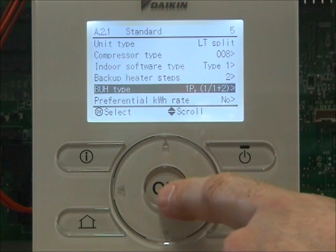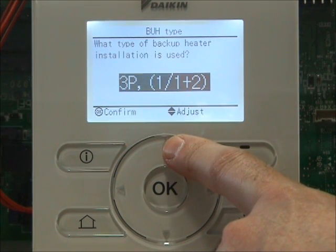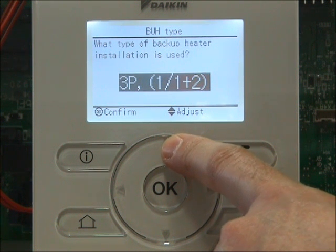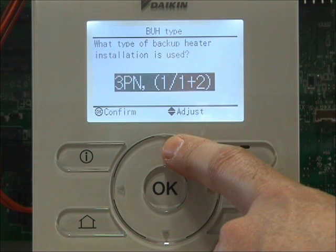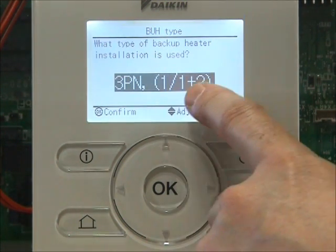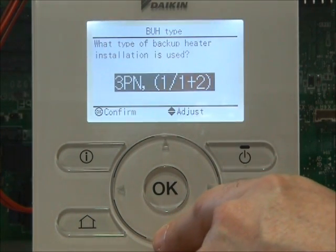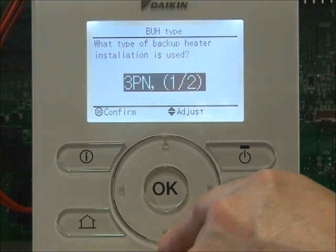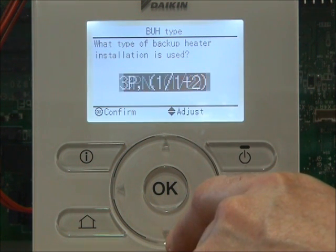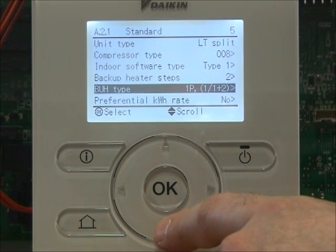Backup heater type: 1P is single phase, 3P is 3 phase, 3PN is 3 phase and neutral, and 1/1 plus 2 is 3 phase and neutral 9 kilowatt heater. 3PN 1-2 is 6 kilowatt heater. So you've got single phase, we'll select single phase on this one.